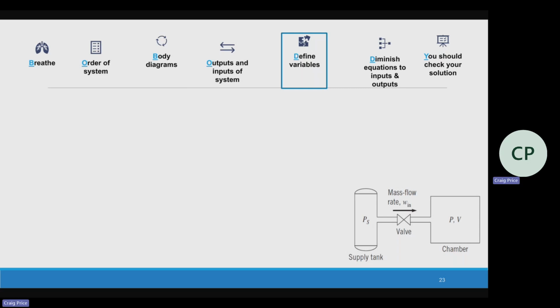So for definitions, the first one is very similar to hydraulic. We have a Cp dot, so capacitance times pressure dot, equals the net change in mass. I could write it as m dot, which we could say is the sum of all mass flow rates in minus the sum of all mass flow rates out.